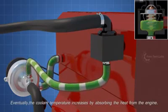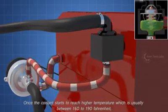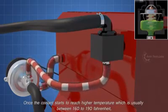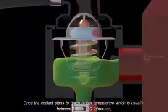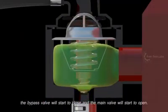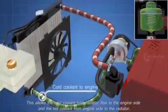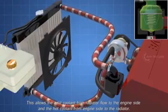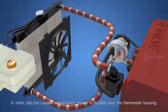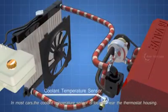This helps the engine to heat up to operating temperature quickly. Eventually, the coolant temperature increases by absorbing the heat from the engine. Once the coolant reaches a higher temperature, which is usually between 160 to 190 Fahrenheit, the bypass valve will start to close, and the main valve will start to open. This allows the cold coolant from the radiator to flow to the engine side, and the hot coolant from the engine side to flow to the radiator.